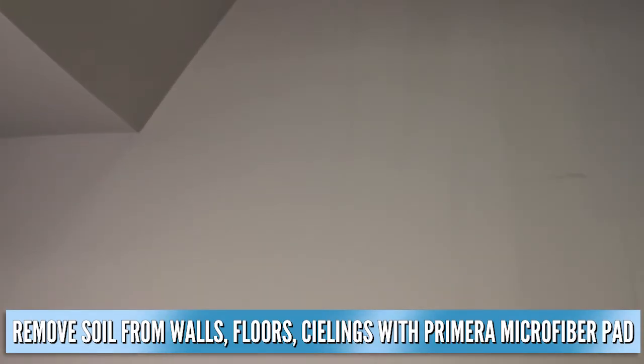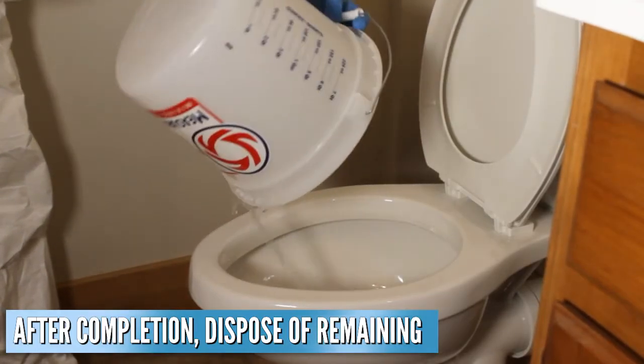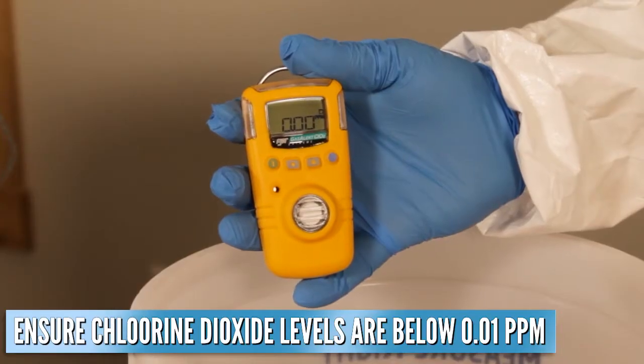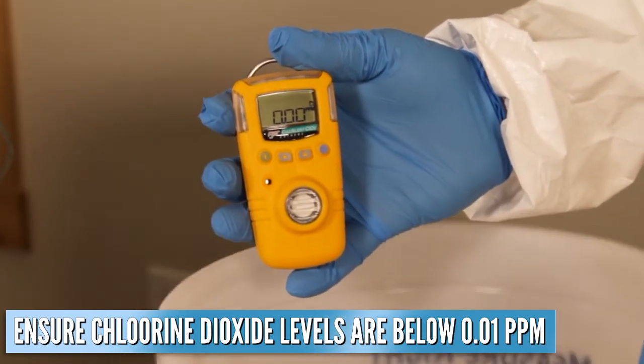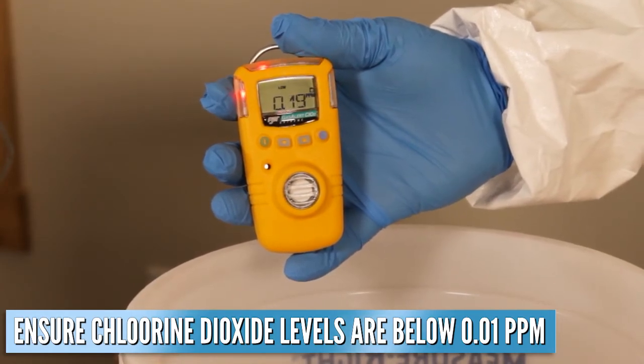The remaining soiled chlorine dioxide solution can be flushed down a toilet or poured into a sink for disposal. Test the space with your chlorine dioxide meter to ensure that levels are below 0.01 part per million before authorizing reoccupancy of the space.